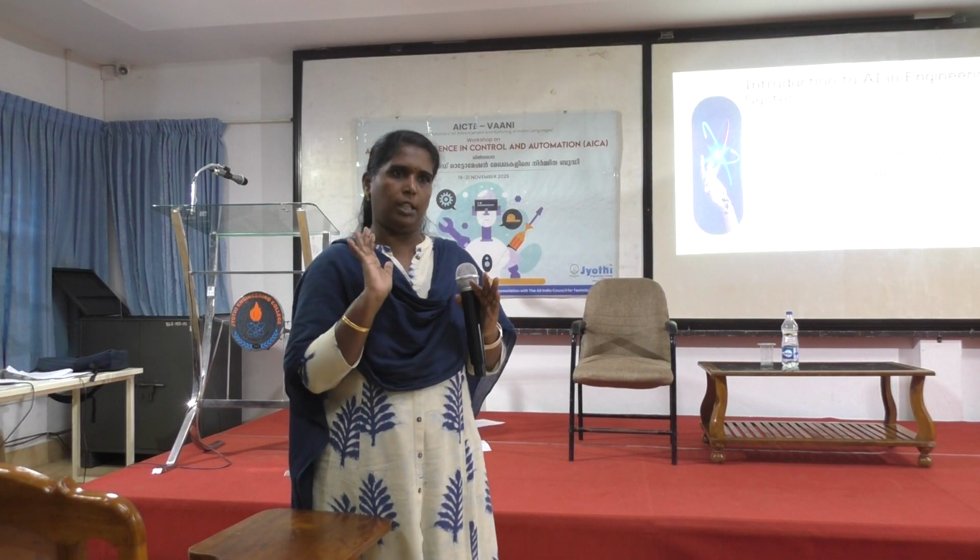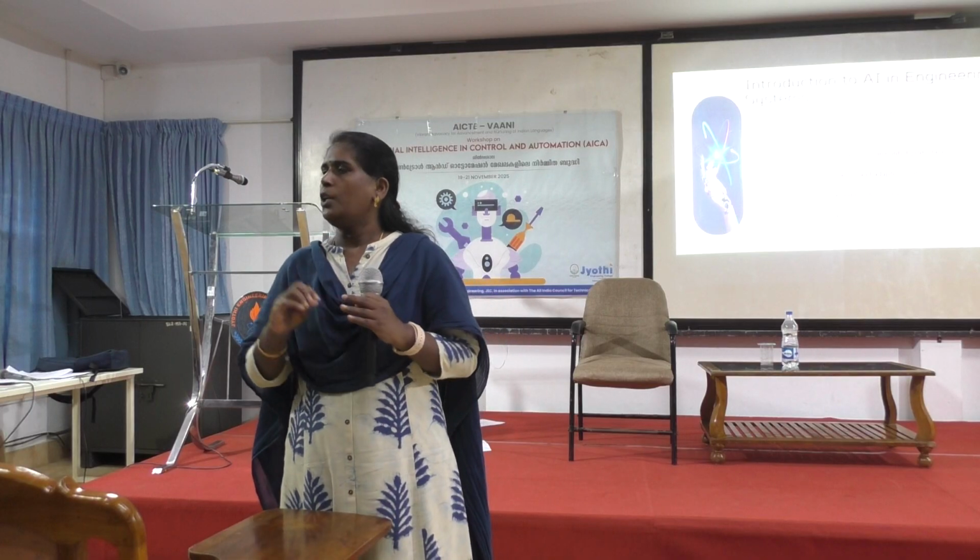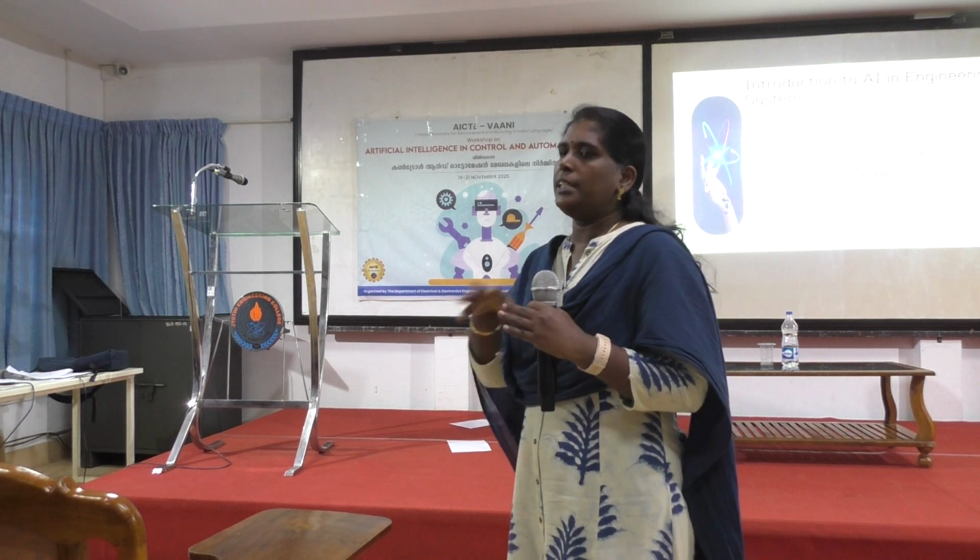Now if it is coming out of the range, you are designing the PID control for a particular region or operating point. If the error goes outside that, the same equation applies, but the controller has a minimum and maximum input value, 0 to 100. The controller can open 0 to 100, after that it cannot open, it is 100% open. So now what to do? Whether to decrease it or increase it? In that kind of situation, AI will think how to minimize it, or whether to give an alarm. That is the adaptive control.